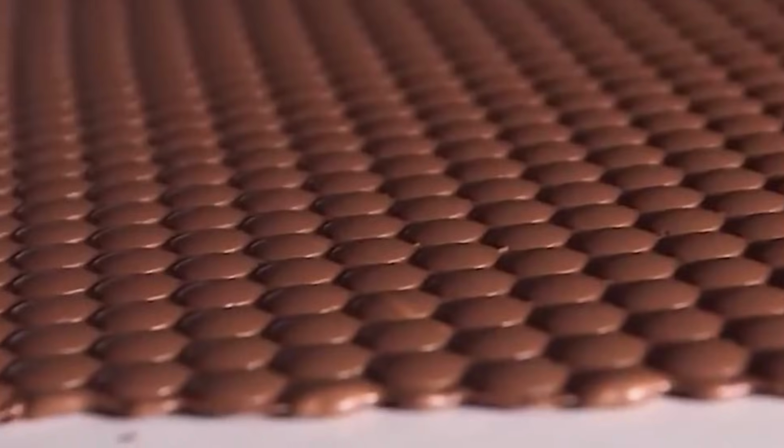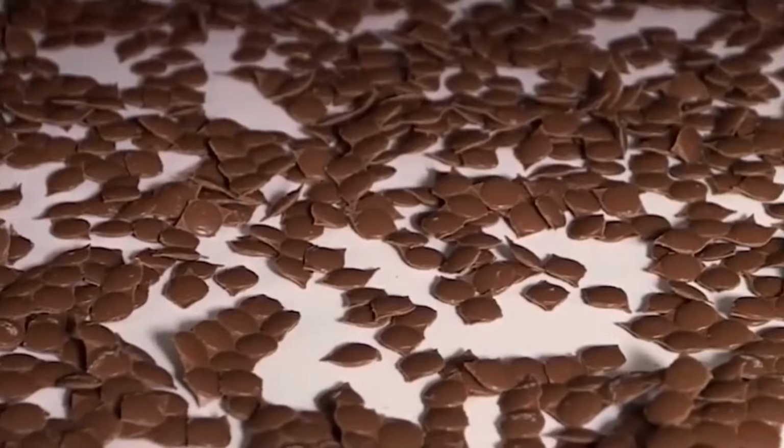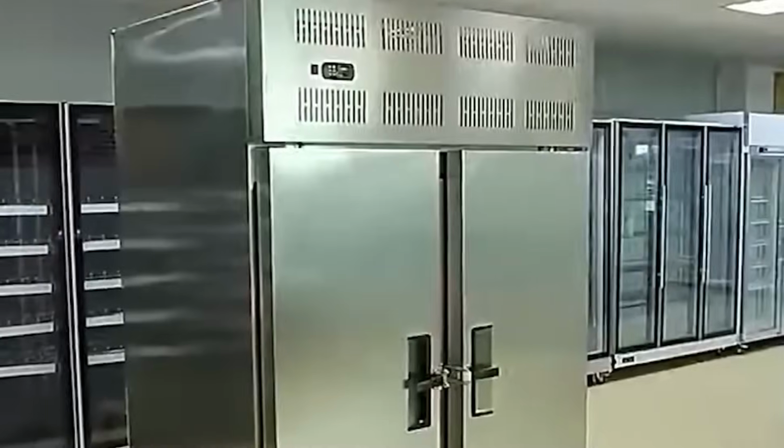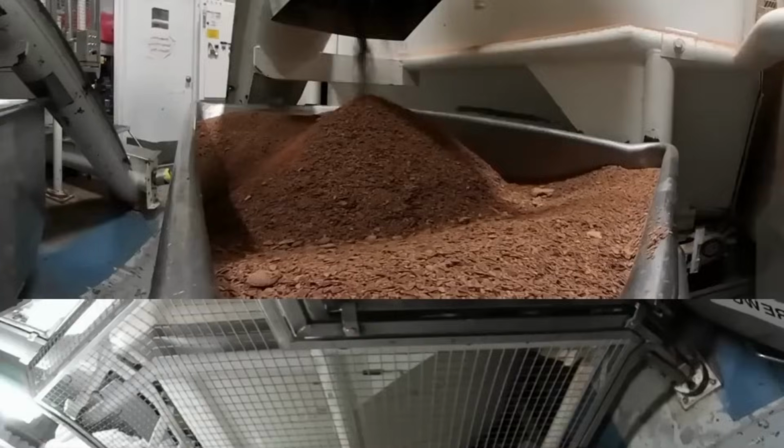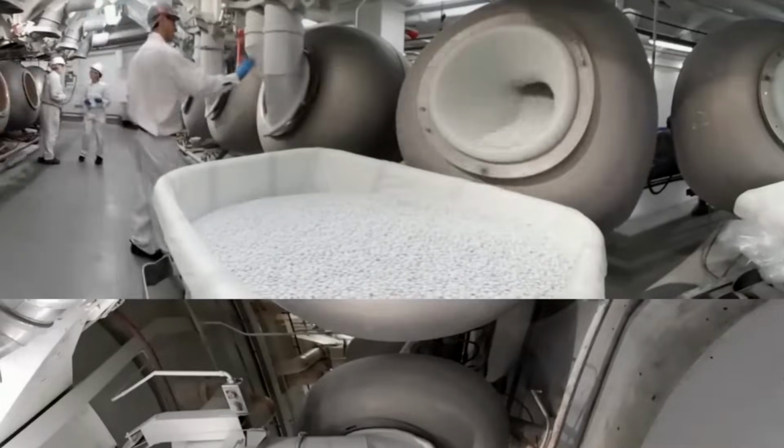Specific gravimetric dosing pumps ensure each batch receives a uniform mass of syrup and colorant. Standard M&M's caramel products are colored using a fixed ratio of FDA-approved colorants, with pan scheduling arranged to avoid cross-color contamination. Each color batch is tracked with a unique identifier linked to its dye lot and pan ID.